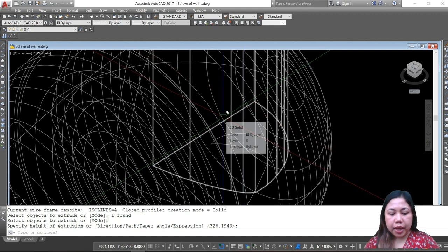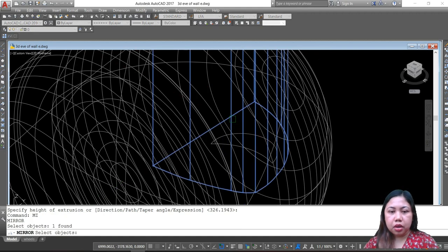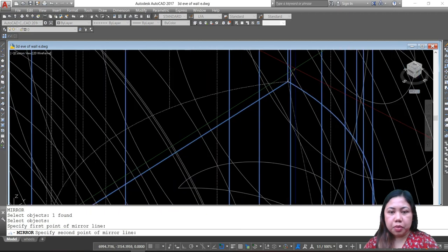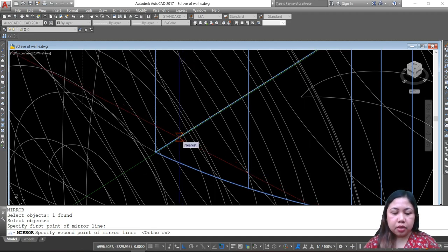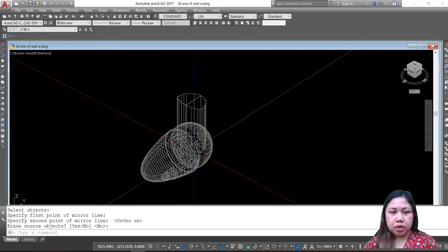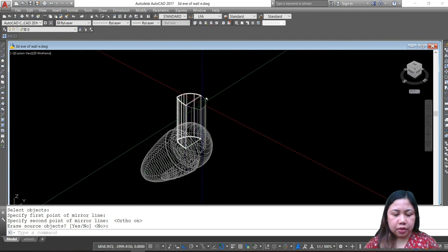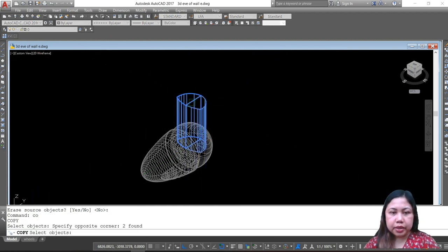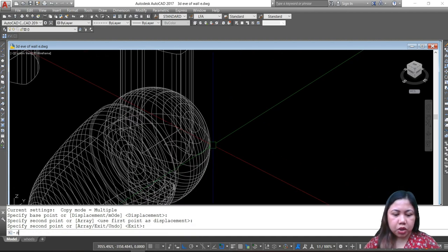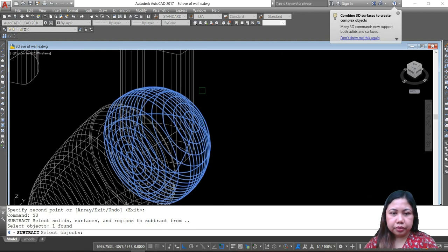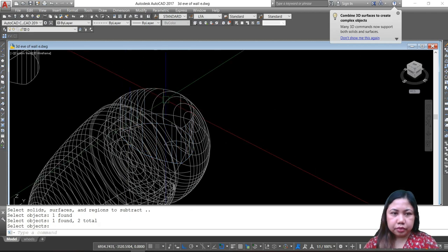And then command MI, mirror. You mirror the face. Turn on the ortho. So you have this face already. So you copy this. You subtract. Okay?